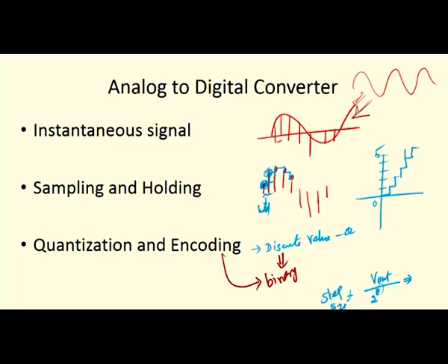During that time, it has to wait instead of getting the next magnitude. So, this one is sample and hold. First, this value will be taken and converted into a discrete value, which is the process of quantization. Then it will be converted into its corresponding binary representation.